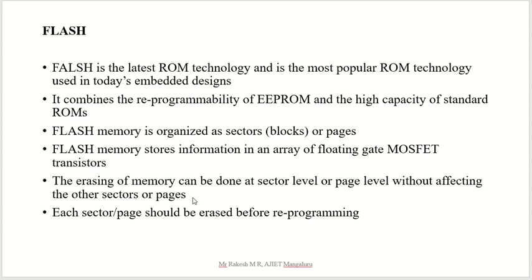Another advantage: if you divide the entire flash memory into sectors, blocks, pages, you can program only a particular page or you can erase only that particular page. That is the thing we have in flash memory. Here this line represents the same thing: page level without affecting the other pages.